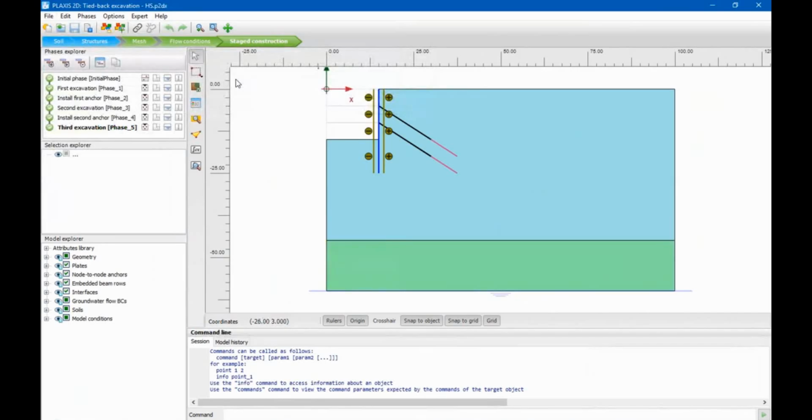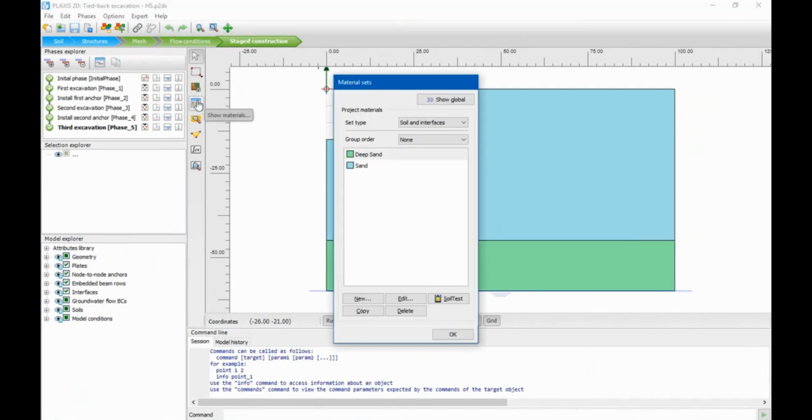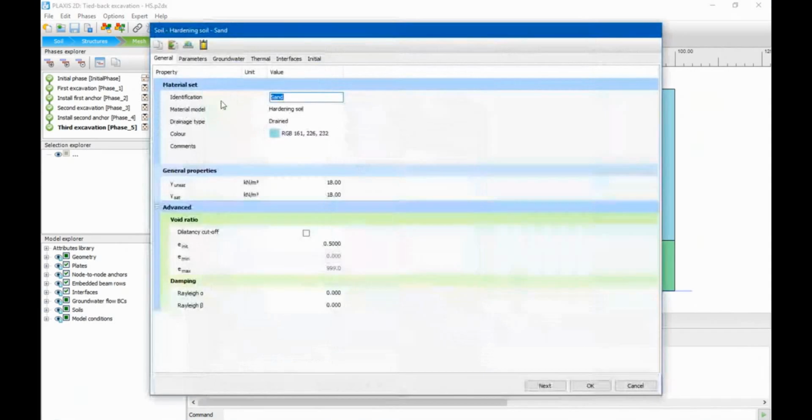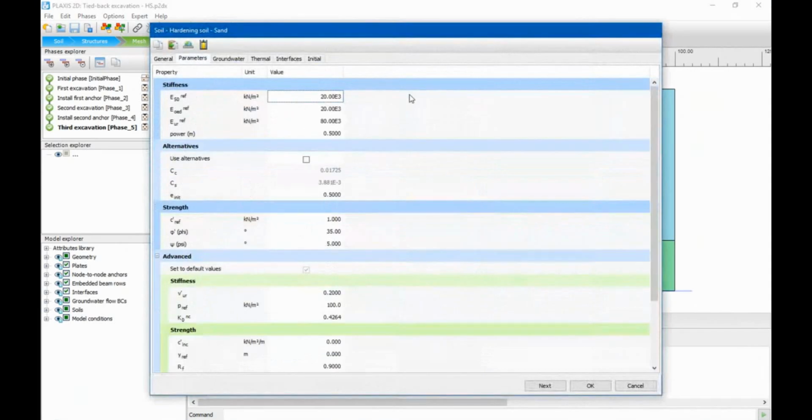So what you see here is that the first 3 layers of the Mohr-Coulomb model that just have an increase of stiffness with depth simply because the stress levels increase is now modeled with the hardening soil model. But the hardening soil model does not have this facility to make an extra stiff layer because the strain levels are so small. So that I had to introduce myself, which is the green layer at the bottom. So if you look at the parameters for the sand, those first parameters are exactly the same as we had for HS small.